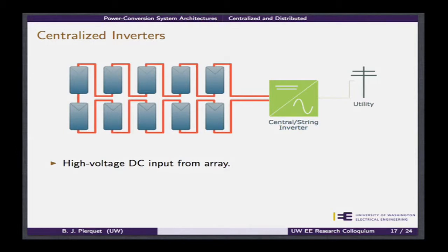If you decide to disconnect the central inverter, it really doesn't matter, because if there's sunlight outside, that array has voltage. And it becomes a relatively large safety issue, and so there's a fair amount of effort that goes into protection mechanisms, insulation of wires, and all sorts of different standards that have to be followed in order to get this to essentially meet code.